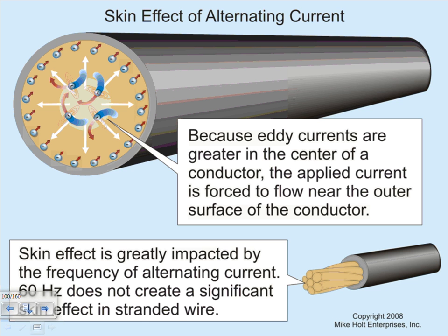I think it's a great example of skin effect, because your current is going to the surrounding of the wire, so the core, you really don't care if the steel is carrying current or not. You care about the aluminum around it that's carrying current. The steel is there to carry the weight of the conductor.